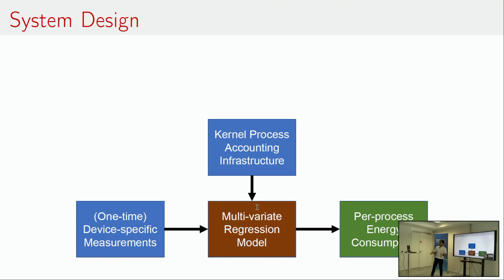It will induce some load, and we can reduce it in two ways. One, you optimize this model, and two, you decrease how often it runs. So instead of running it every 5 milliseconds, you would run it every, let's say, 20 milliseconds. Does that answer your question? Why can reducing the frequency reduce the energy consumption? Whenever this module runs, it wakes up the processor, and then the processor has to do something. Yes. And because the processor is doing something, there's a spike in the power consumption of the system.